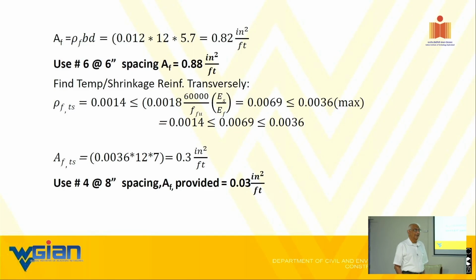We even proportion the coarse aggregate. That's another stringent requirement for us, like 3/4 or ½ inch. But for geopolymer, we only go max ½ inch. Without it, believe it or not, we didn't get a modulus of more than 1 MSI, like 6, 7 GPa.